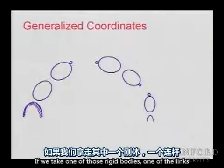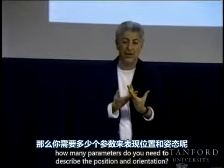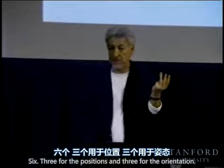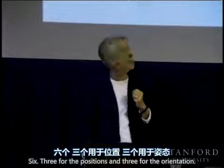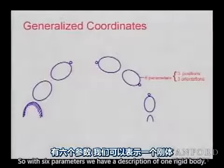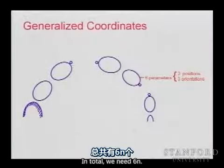If we take one of those rigid bodies, one of the links, how many parameters do you need to describe the position and orientation? 6. 3 for the position and 3 for the orientation. So with 6 parameters we have a description of one rigid body. Now we have n moving rigid bodies. In total we need 6n.